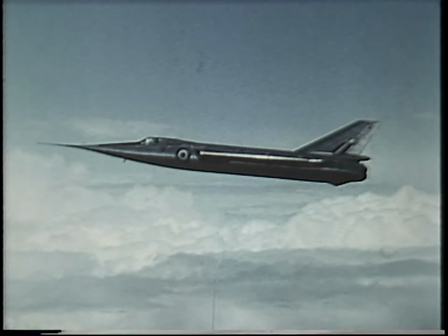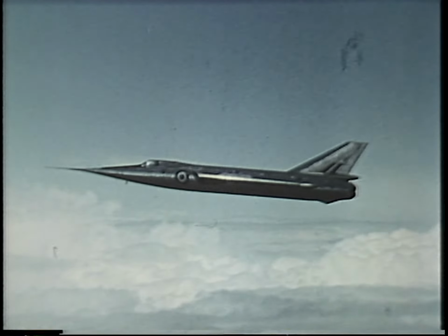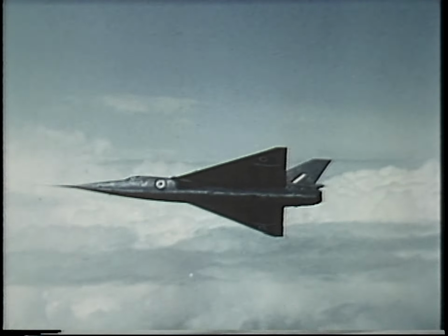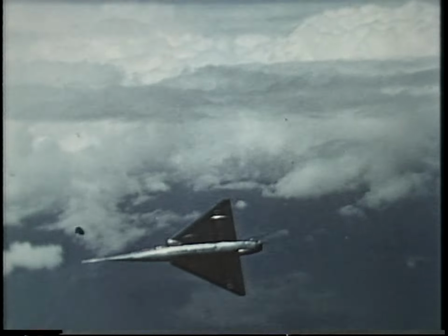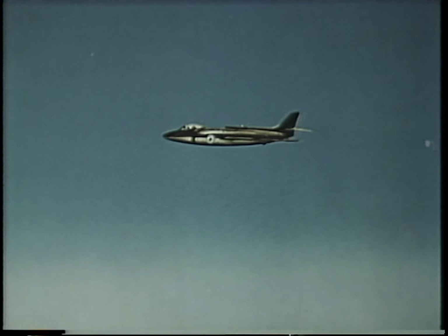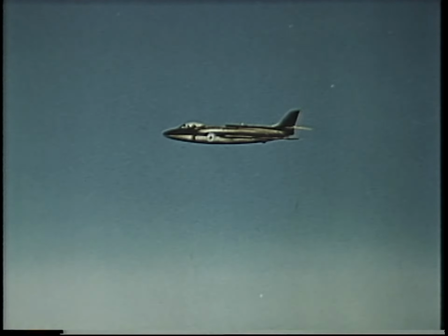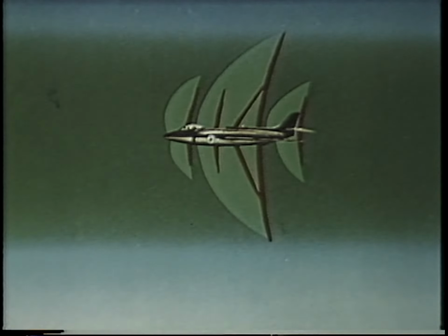And what about aircraft which have to fly much faster than sound? Designers of such aircraft have had to accept the presence of shock waves and find ways of overcoming their effects. Above the critical Mach number, speeds are grouped into two ranges. The transonic range covers speeds at which the airflow is mixed, part subsonic, part supersonic. Here, subsonic airflow is shown in dark green and supersonic in light green.